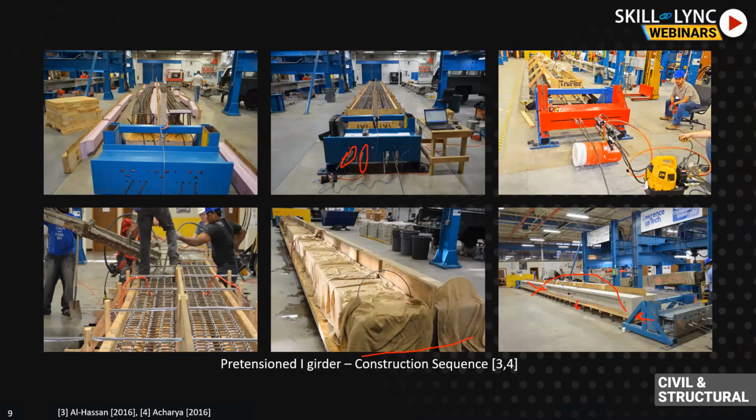So obviously a couple of things come into play here. Because of the initial prestressed force in the strand, the beam tries to buckle like this, right? And that is how it develops something called camber. But again, because of its self weight, there is a uniformly distributed load in this direction, so it will try to bend like this, right? So some of the camber will be neutralized by the self weight deformation. All these things come into play when you really dive into prestressed concrete. You look after all these things.